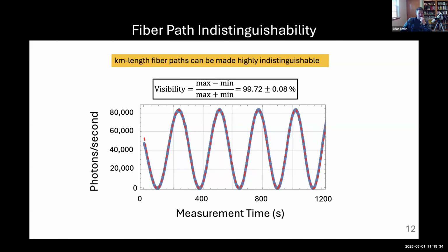Supposedly that's what I've heard, but from the measurements that we've made, I don't see it. I think that the fiber itself is important for these measurements. Krister also uses a different version of this that's very polarization stable, with a nice jacket. We actually see very bad results if we just use the 900 micron jacket. It's just not insulating enough. So you need something with an adequate jacket. For sure. Okay. Good to know.